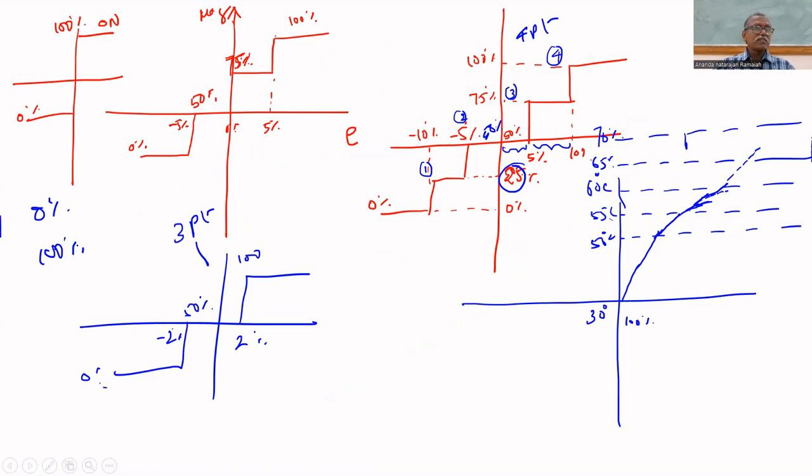We are giving 50% power input. So we can vary the voltage. If 100% means 220 volts, let us assume, 0% means 0 volts, and 50% means 110 volts. Like that, we can vary the voltage. So some arrangement is there, and we can give 3-point control. For the next one, we can give 25% voltage, 50% voltage, 75% voltage, or 100% voltage: 0, 25, 50, 75, 100. So that is 5-point, not 4-point. So a 5-point controller.